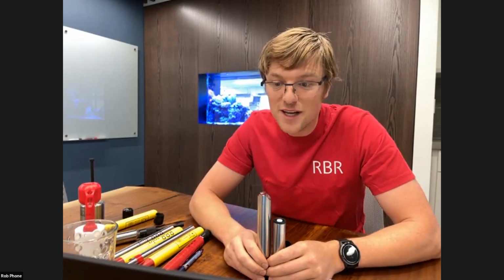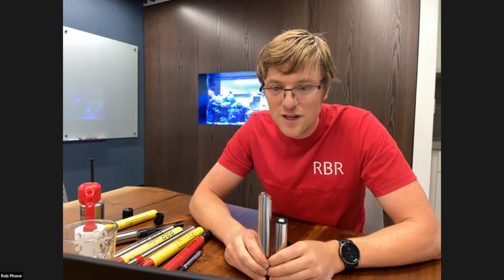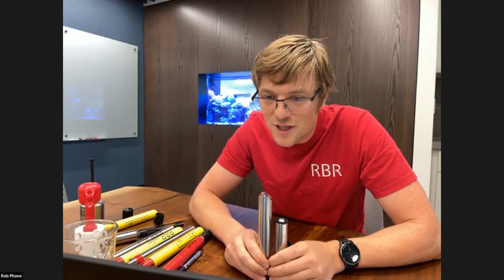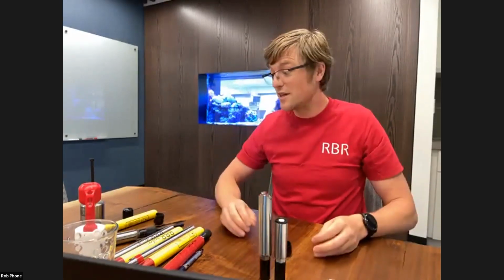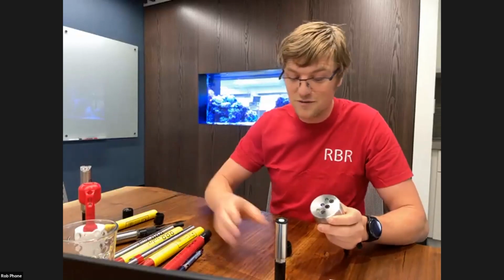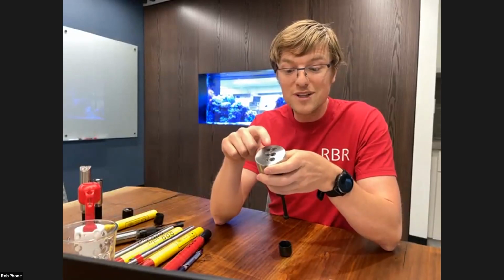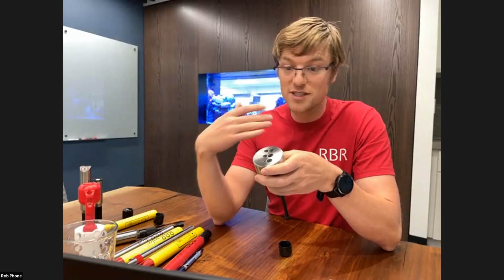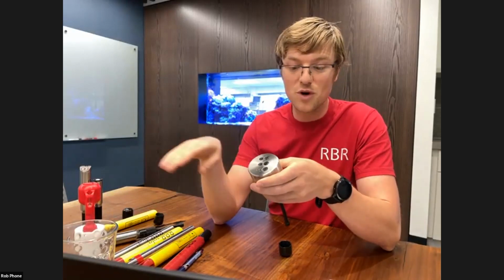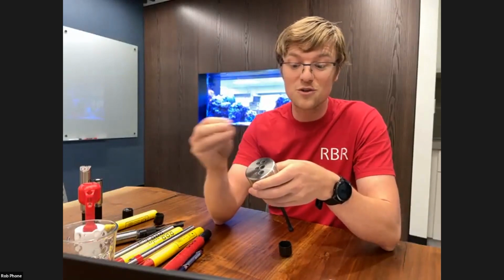Another question here about backscatter measurement. The 1 milliliter sample volume sounds so small compared to the volume of the body of water. I'm assuming the turbidity is generally pretty constant through the water column, so that taking a big series of 1 milliliter measurements is sufficiently accurate. Yes, that's exactly right. We are doing quite a lot of measurements. This particular sensor operates at 32 Hertz. That 1 milliliter volume is quite small, but it's being flushed constantly. As this thing moves through the water, at 32 Hertz, it's basically measuring quite a new parcel of water quite rapidly.